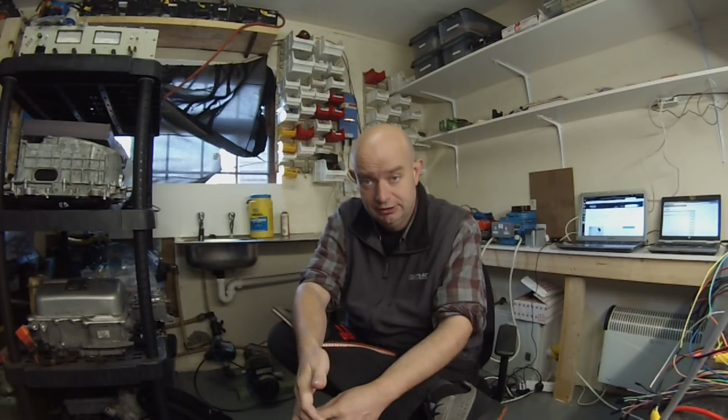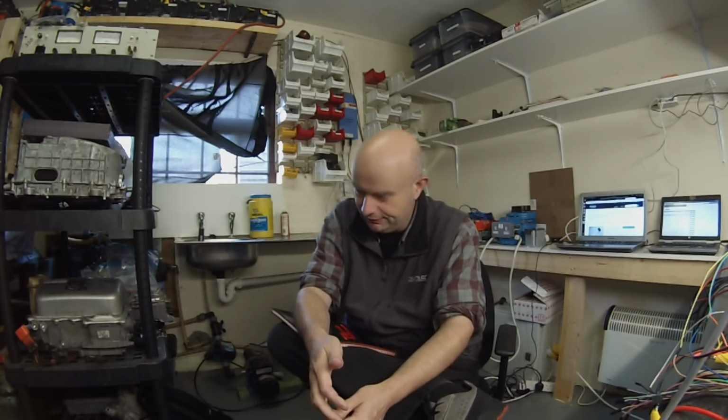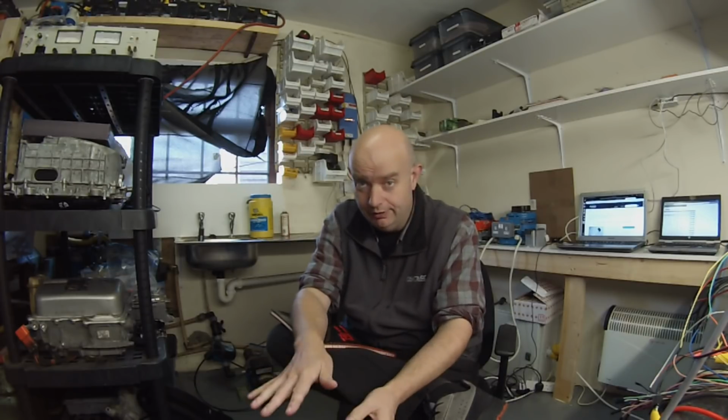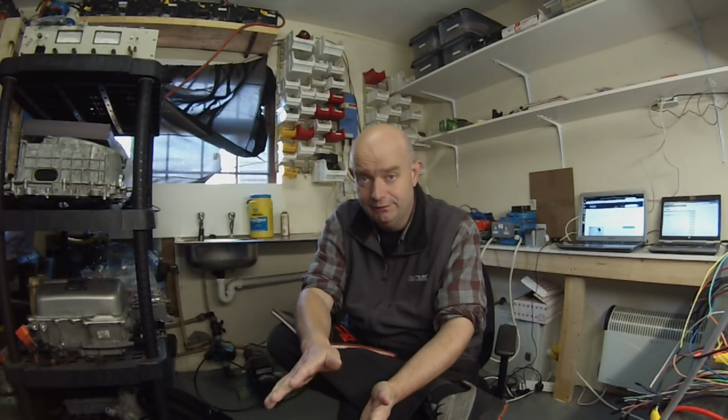The first, which is the default, is called all off. What that means is that when you detect a hardware overcurrent event, you always shut down the IGBT drivers anyway. But what you do then is you shut off the main contactor and shut off the pre-charge relay. So that's the default condition.